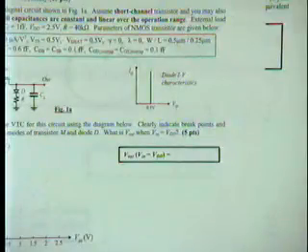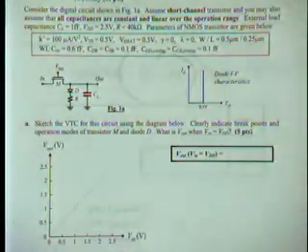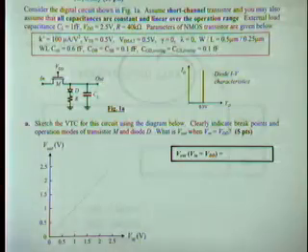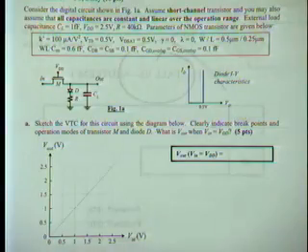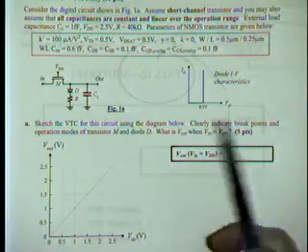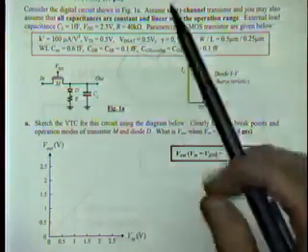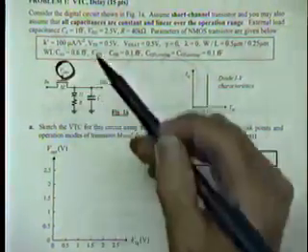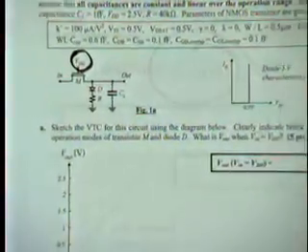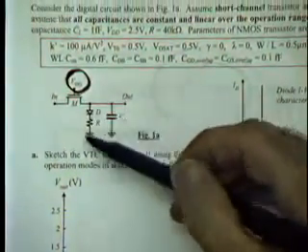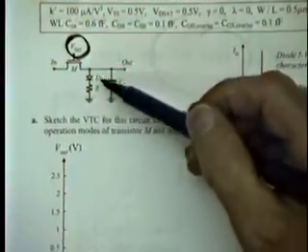This is an interesting one. Definitely worth considering and studying. It's where you have a very weird gate, a gate that is kind of bizarre, in the sense it consists of an NMOS transistor with its gate always at VDD, and then a bizarre load network consisting of a diode and a resistor.